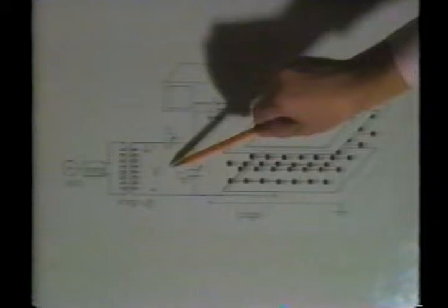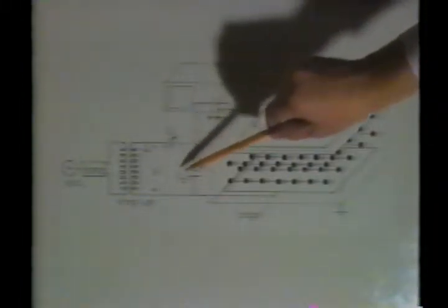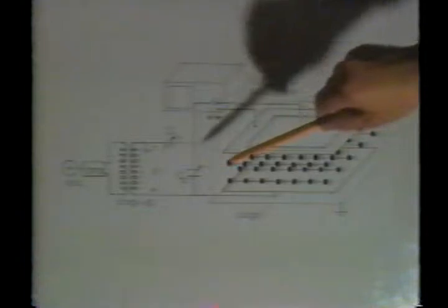These capacitors are in the other legs of the bridge. It helps to draw the circuit like this. Here are the ping-pong balls. These capacitors are those of the balanced amplifiers on the scope. So the oscilloscope displays the output voltage, V sub 0. With the array removed, this capacitor, C sub 2, is adjusted to null the output voltage, V sub 0. The output voltage resulting from the insertion of the array is a measure of the change in capacitance.